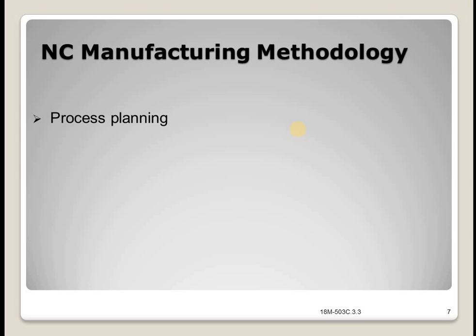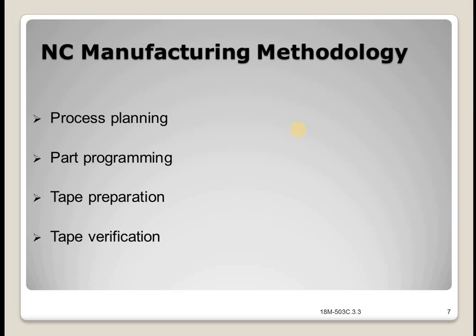NC manufacturing methodology. The steps which are followed in NC manufacturing are process planning, part programming, tape preparation, tape verification, and finally production.